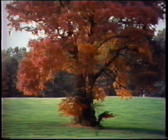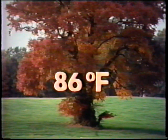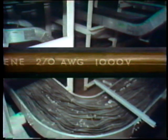Ambient temperature is the temperature of the area in which a conductor is installed. But since the ambient temperature changes with the seasons, if not day to day, a standard was established for ambient temperature. That standard is 86 degrees Fahrenheit. The other factor, internal temperature rise, is the amount that the temperature of the conductor rises above ambient temperature when current is flowing through the conductor. The amount of current flow that causes the conductor to reach the maximum operating temperature limit is what's called the allowable ampacity of the insulated conductor. The allowable ampacity of an insulated conductor and its maximum operating temperature limit go hand in hand.